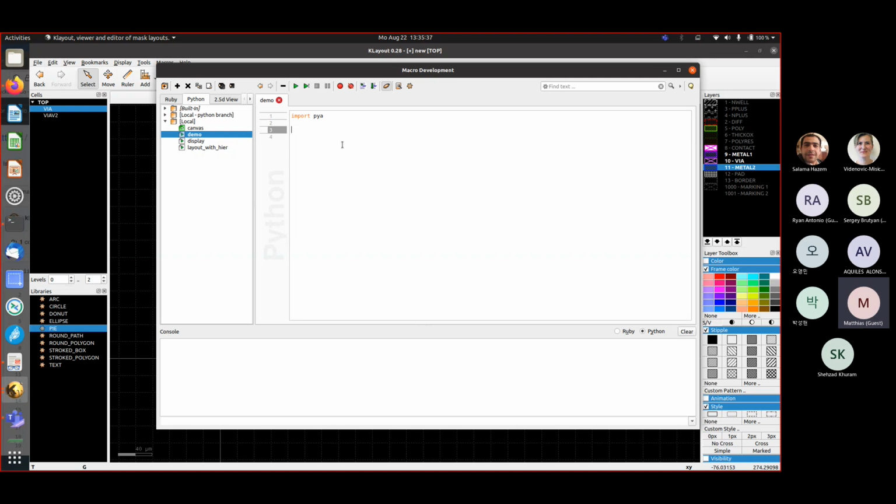Is there a way to know which version you're in? Do import klayout inside KLayout? Yeah, the problem is that, when you install KLayout on Windows, it comes with its own environment, because in Windows there's usually no system Python. My own environment means I pull in all the shared objects, DLLs, and whatever comes with Python. And I didn't pull in the whole system, including pip and so on. And even if I did, I would need to give you some command line which then accesses this environment.